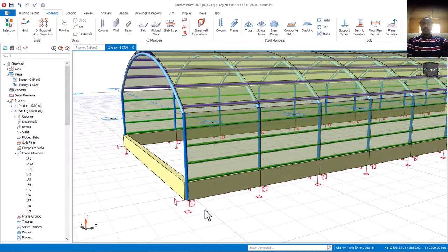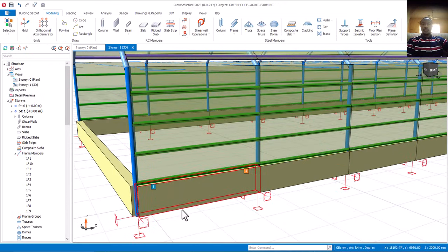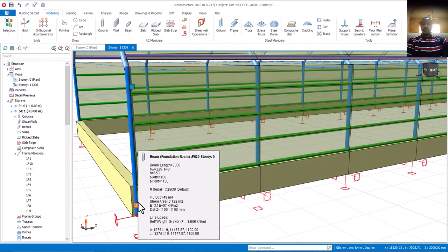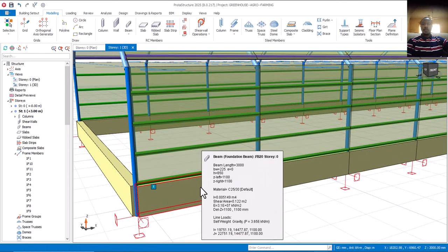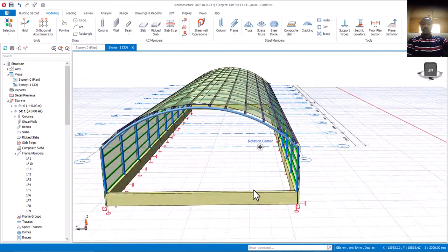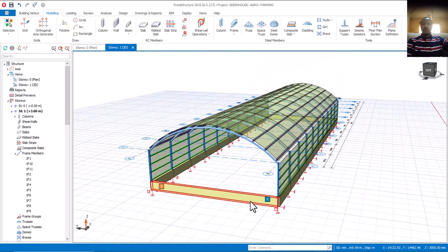If not, you can imagine this particular space here. We'll have used a pedestal for each of them, instead of having all this reinforcement along this path, in which we can raise block and fill it. But this place is going to be a reinforced concrete around this column, which is our pedestal. The other places are just block to connect them and move on. If this is what the design is saying, automatically you have to design based on this. All right, that is fine.